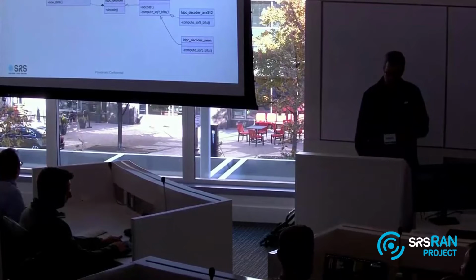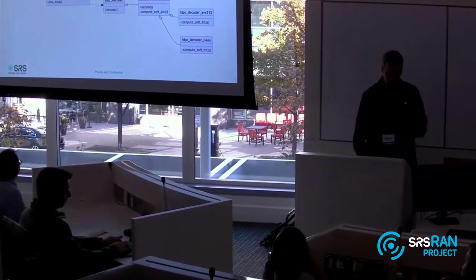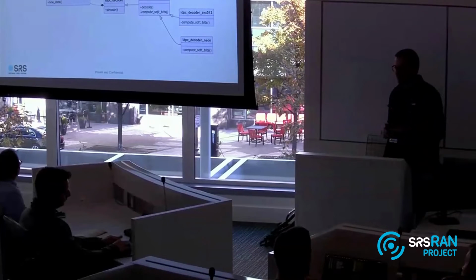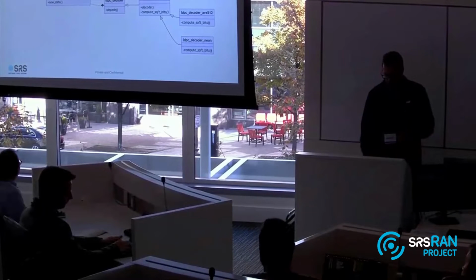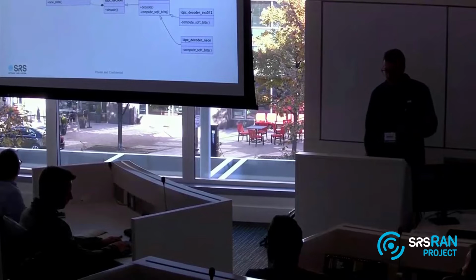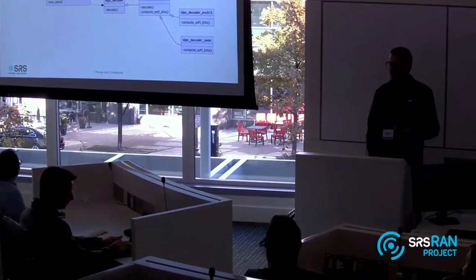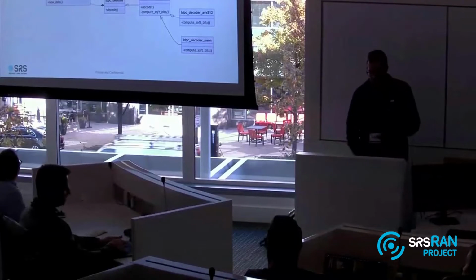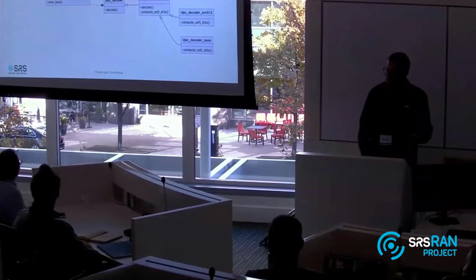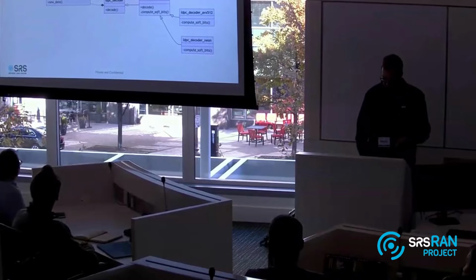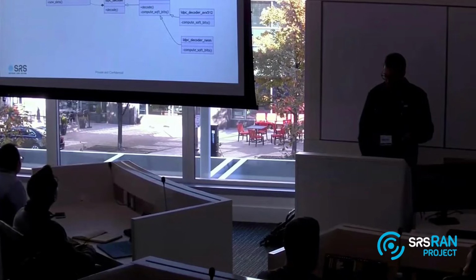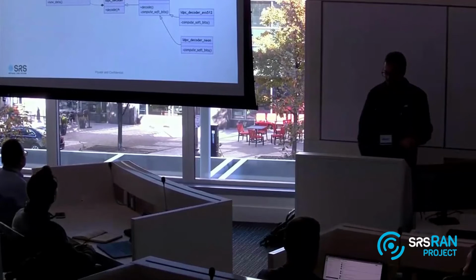We have an interface like the PUSCH decoder that will have a method that says new data arrives, process it. In this case, we can have 2 implementations: one that would use the ACC100 in look-aside mode, and one that would use a software implementation. This software implementation will use 2 blocks, the rate dematcher and the LDPC decoder.